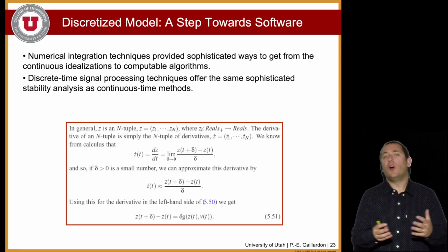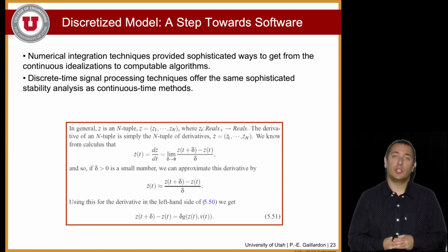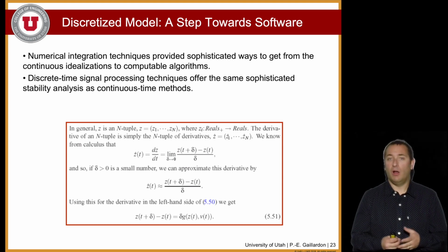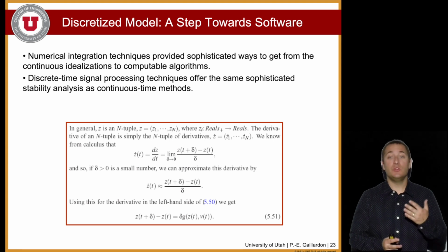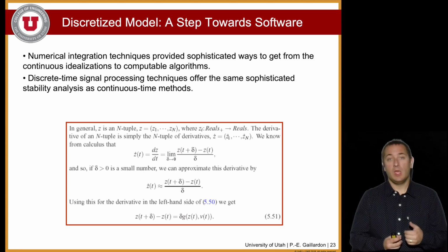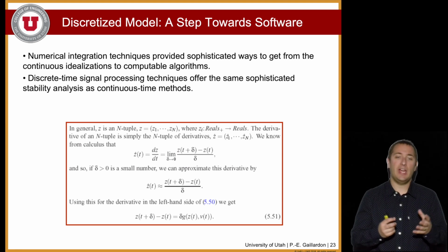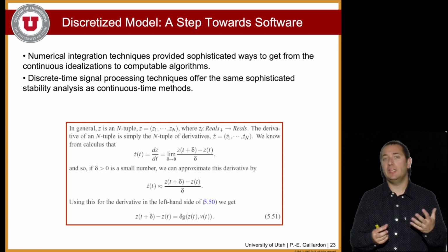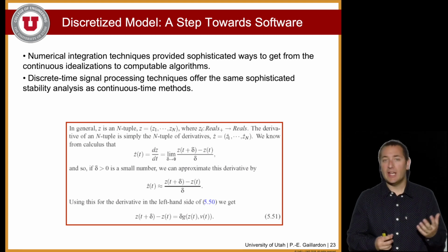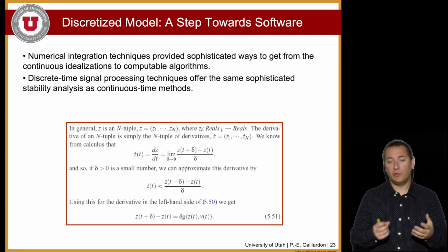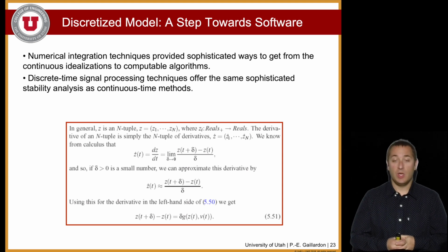Now, so far, I only talked about continuous dynamics, right? So we're talking about the time domain, any varying quantity over time, but most of our systems are digital and use discretized models, for which you will have to consider not anymore the Laplace transform, but Z transforms. And the beauty of that is that most of the theory I did talk about already will still apply in this particular case.